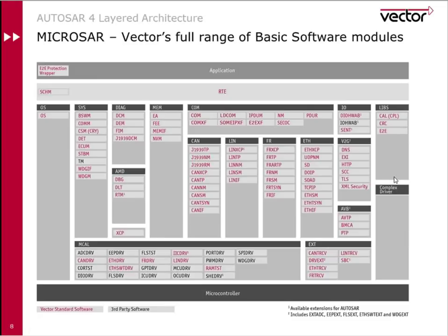If anything isn't quite defined within AUTOSAR, or if anything needs to access the hardware very, very quickly from the application down to the microcontroller without going through the entire layers of the AUTOSAR stack, then it can sit here as a complex driver. So technically, for example, an I2C driver may sit in here as a complex driver because I2C functionality is not formally defined within AUTOSAR. So in the strictest sense, an I2C driver would sit as a complex driver.